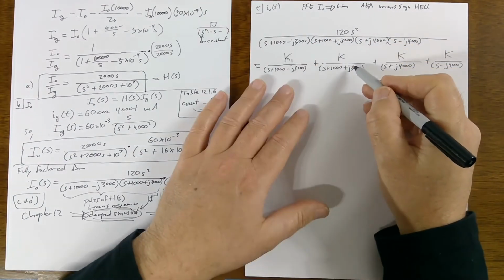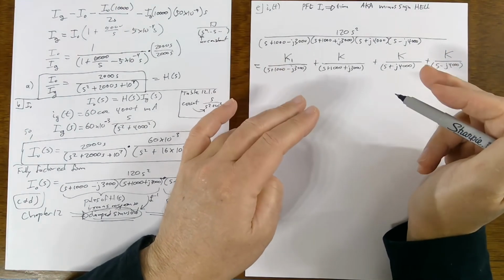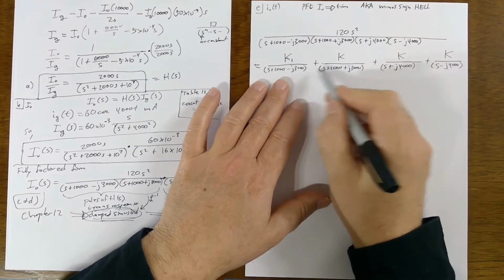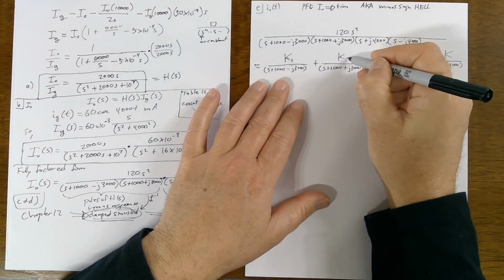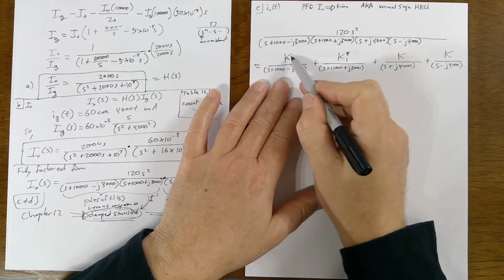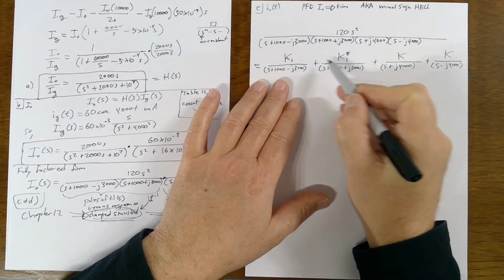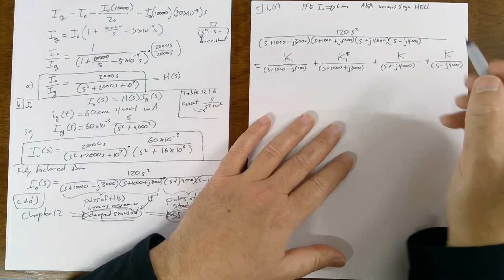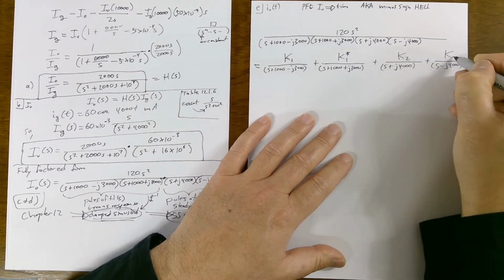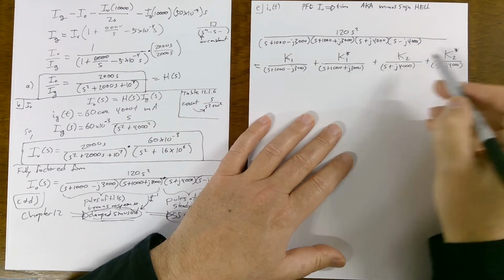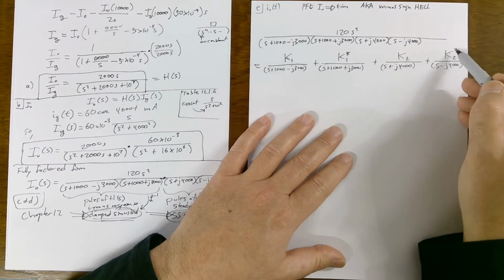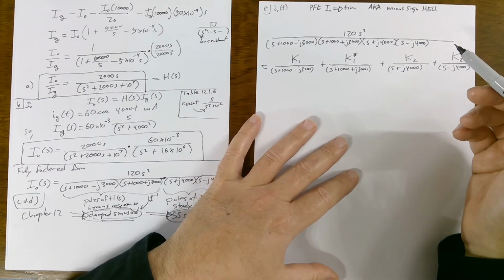Now for physically realizable circuits, that is circuits we can actually build, it turns out that for these kinds of roots, the constants will be complex conjugates of each other. So if we solve for K1, then we know this constant is the complex conjugate of that. Likewise, for these two roots, the constants are going to be complex conjugates. So we only have to solve for K1 and we can get K1 conjugate, and then we can solve for K2 and we'll know K2 conjugate.